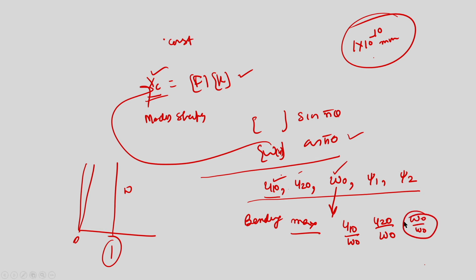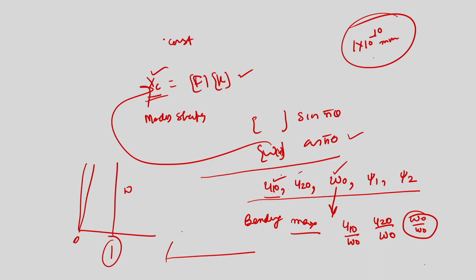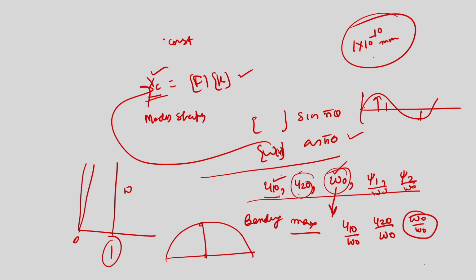You find that in most cases the magnitude is showing 1 when you see the mode shapes of a shell. Because of that we non-dimensionalize again, and when w is maximum we divide by it; if u2 is maximum, then you have to divide all the variables by u2.